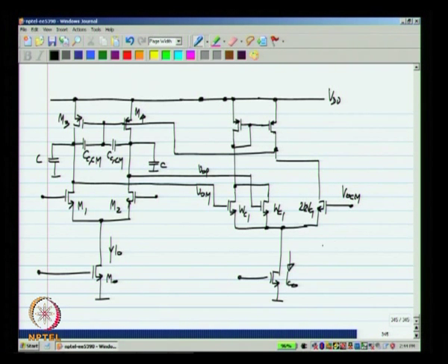and the total current is IC0. Okay. So, this circuit is the same when the op amp is in quiescent condition, when VOP and VOM are equal to VOCM. Now, it turns out that this circuit has some advantages when VOP and VOM are different from VOCM, in how the circuit behaves and so on. It is somewhat advantageous to have this circuit with the two sources tied together than the previous one.